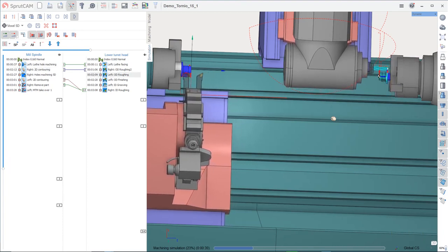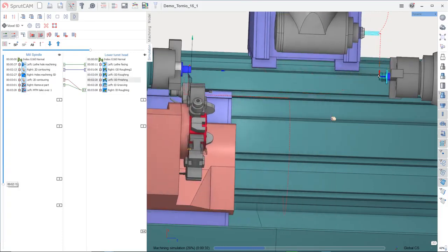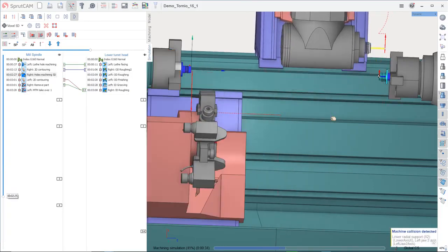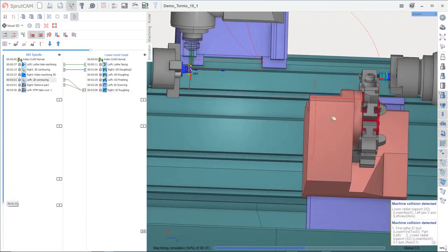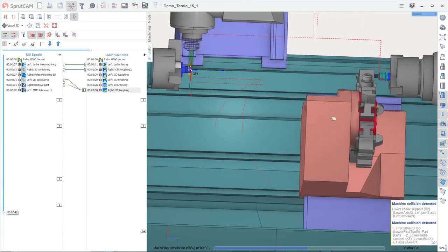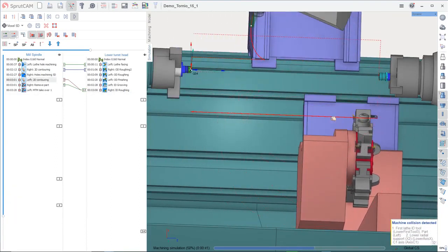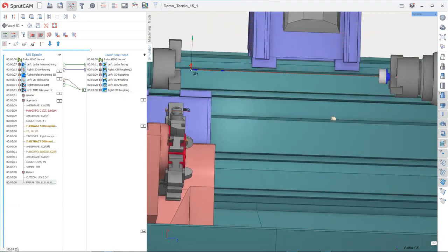After that, you need to reorder the parts in the sequencing mode, and after that you need to add the synchronization points and check everything in simulation. So the simulation can work in 3 modes: simple mode, sequencing mode, and the synchronization mode, and you can check your process in every mode.